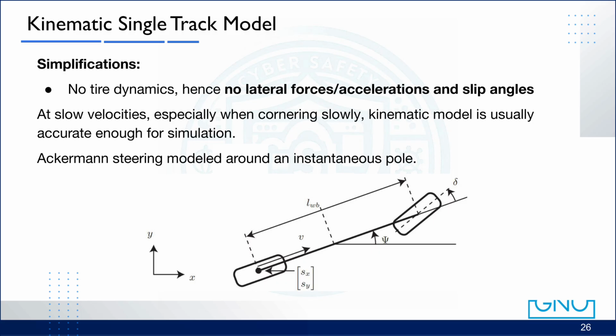This model focuses on geometry and kinematics rather than on the actual physical forces acting on the vehicle. In other words, it completely ignores tire dynamics, so there are no lateral forces, no lateral accelerations, and no slip angles involved in this model. Let's take a moment to explain what these terms really mean.